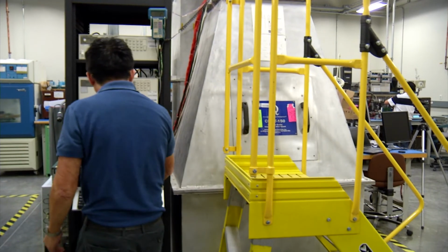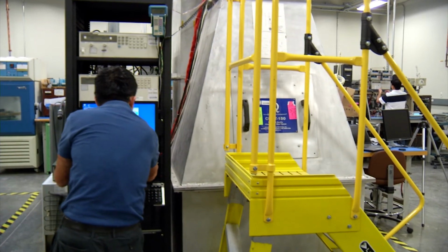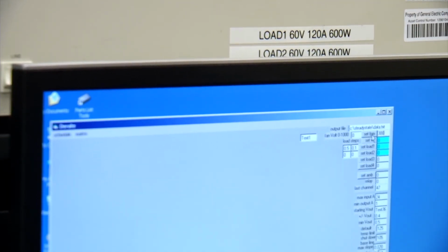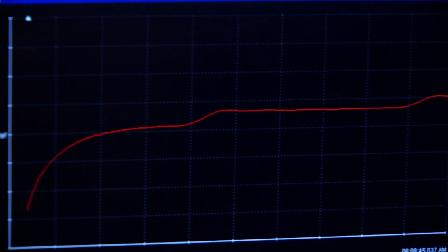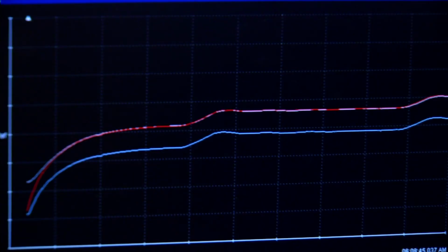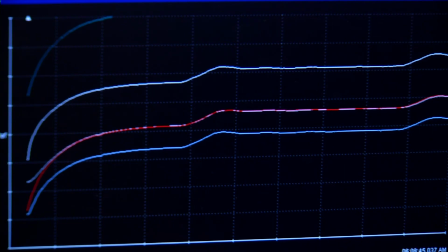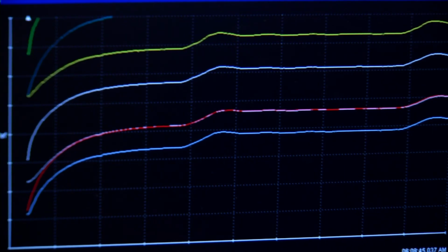The testing is performed using an in-house custom automated test program which continuously monitors all thermocouple component temperatures and continuously monitors and controls the airflow, ambient temperature, and output load to maintain the desired settings throughout the test. It is important that the parameters are continuously monitored and controlled throughout the test because set points tend to drift during testing.